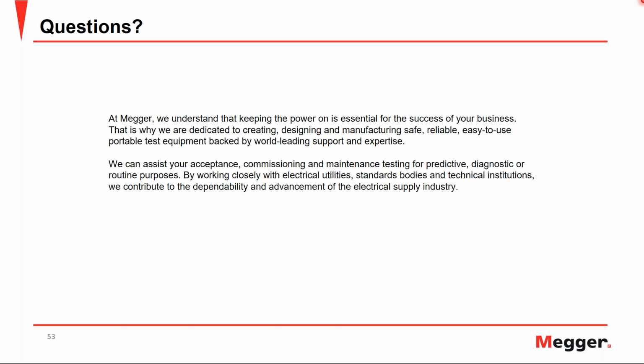Power factor, as was shown with the permittivity equation, is dependent on frequency and temperature. Traditionally we have always done the test at the same frequency, so we were not used to seeing the dependence on frequency. We were just seeing the dependence on temperature, because depending on when we are testing, we will always have a different temperature on the transformer.